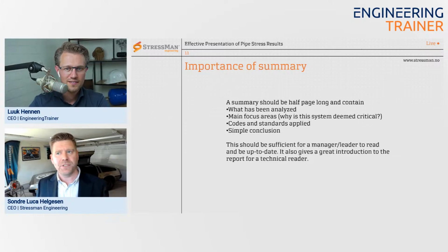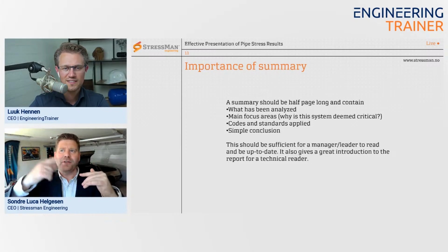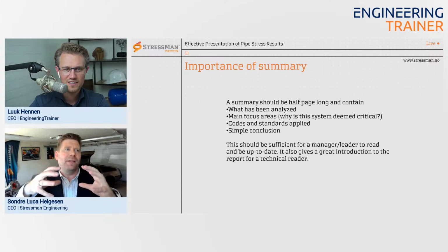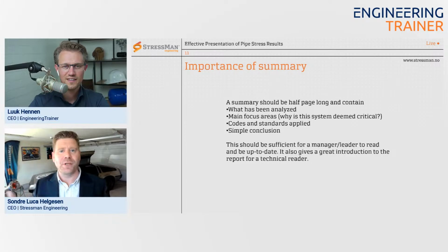But also, I've seen pumps fail due to too high loading, for example. So it's a real problem. They don't fail instantly, because the pump housing can handle the loads, but the shaft going from the motor to the pump will be distorted, and that rotates with a lot of RPMs, and over time that will cause a fatigue failure, or it might be the bearings, for example. So it's more about not distorting the pump, and then we get into another discussion as well.